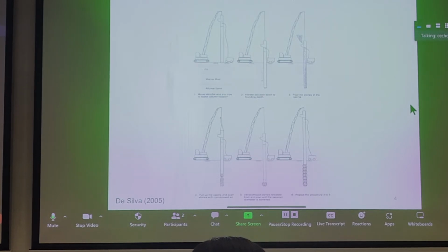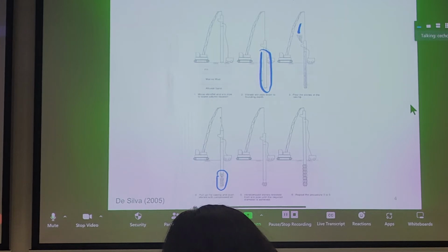You can see that method being carried out chronologically here. In this case, there is a casing being used. The casing was vibrated to the target depth. Then there's a hopper at the top dropping in gravel material. And just like you've seen in the videos, they create balls of gravel all the way to the top until a column is formed.